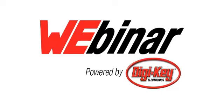Even if this connector is running for a long time, for 10 years and more, the plastic cannot age faster than it should because we respect the relative thermal index. That's why the connector is rated for 105 degrees.